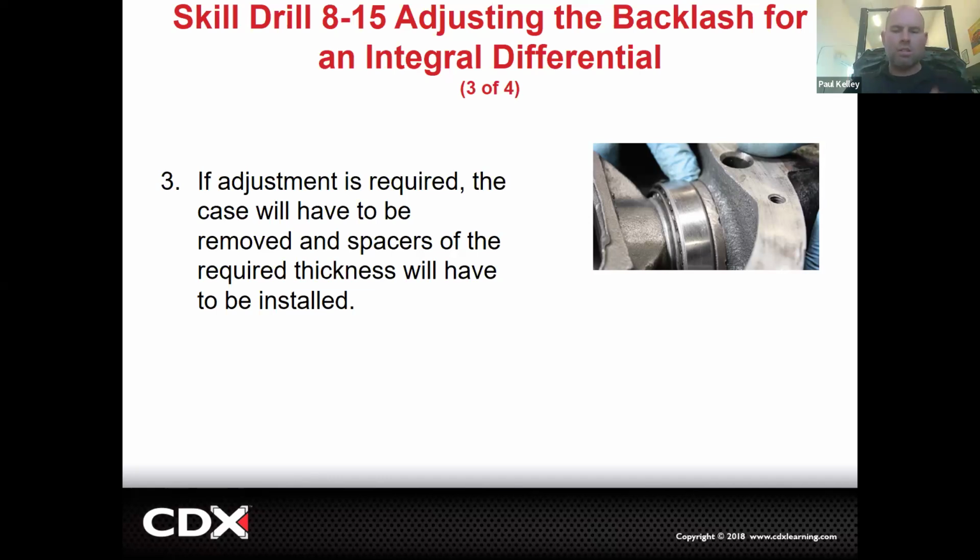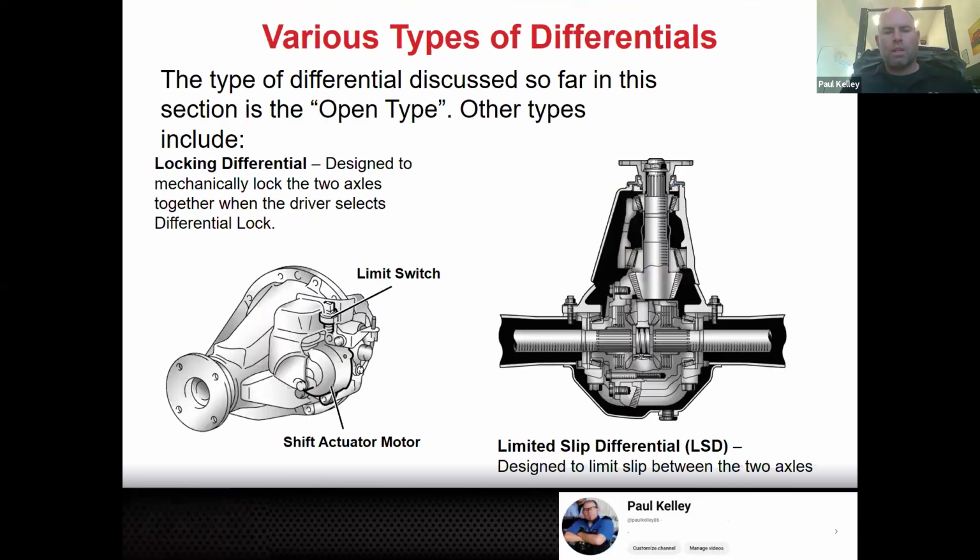The ones you guys are going to be doing at school actually have threaded adjusters. They're amazing. You don't need shims. You can set the preload and the backlash all with threaded adjusters, but they're a little more expensive to make. So most vehicles don't have them because most vehicles never get the diffs done. Like, why give an adjuster that's never touched? Type of thing.